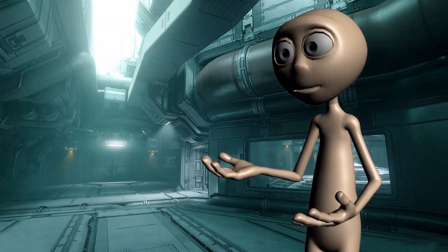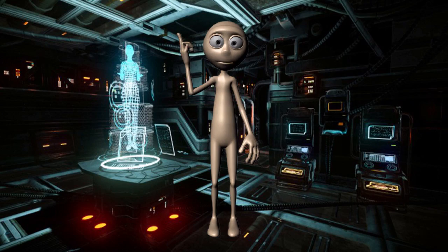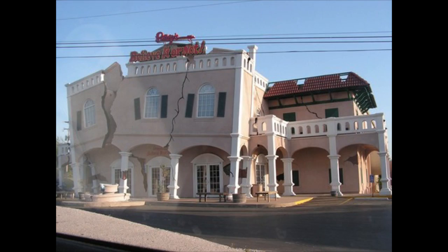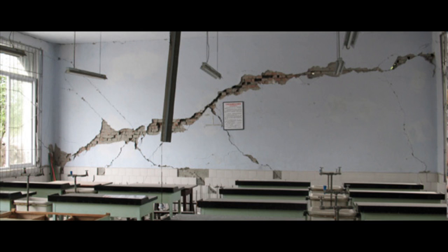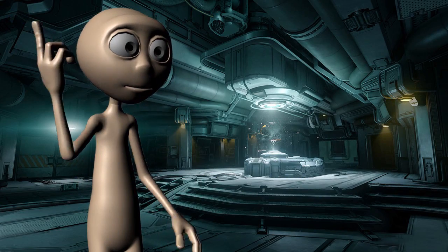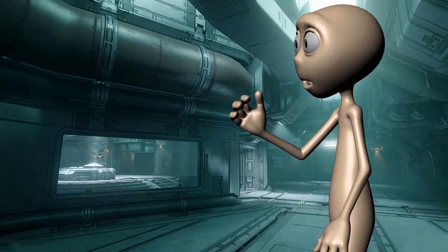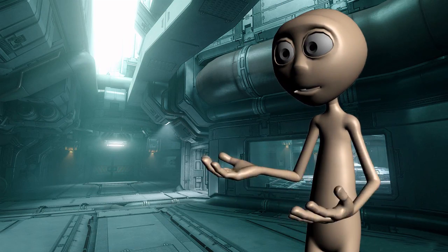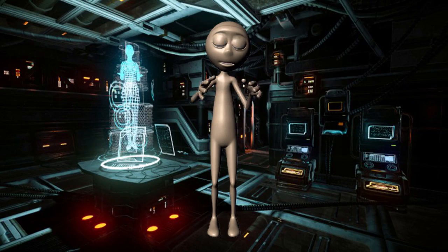If we are not going to perform this test, we won't know how much settlement is to be accepted while designing a structure. One of the troubles faced by the engineer is the structural instability due to settlement. So the objective of the test is to simulate the compression of the soil under expected external loads. And from the results, we can predict the settlement of various soil layers in the field.